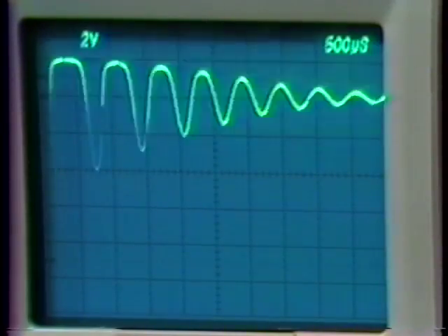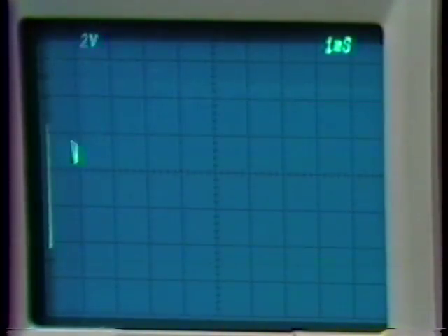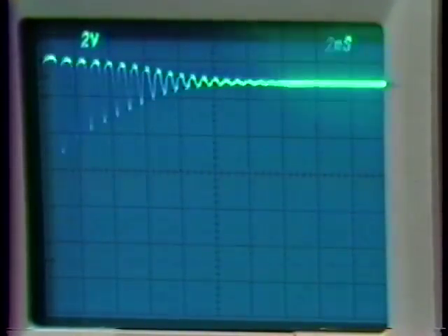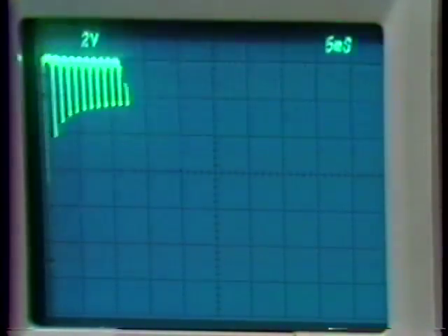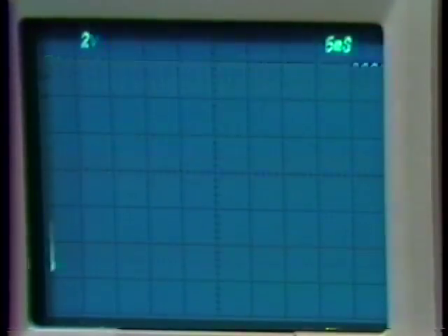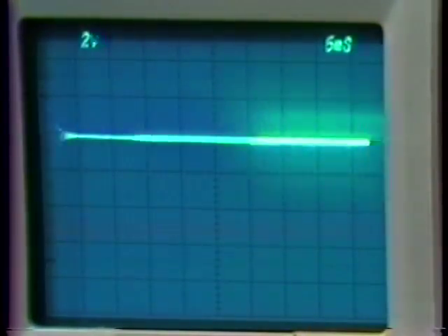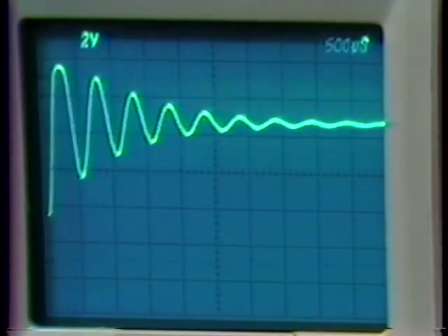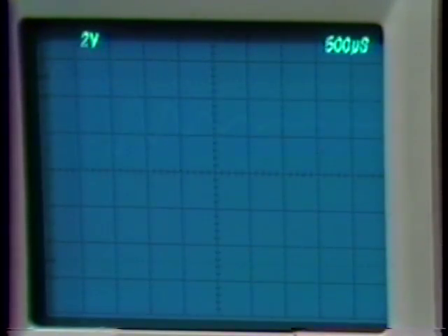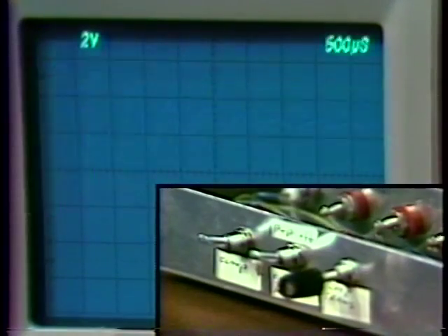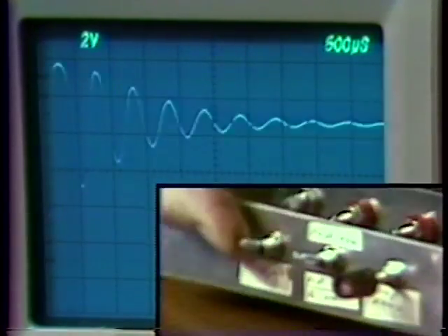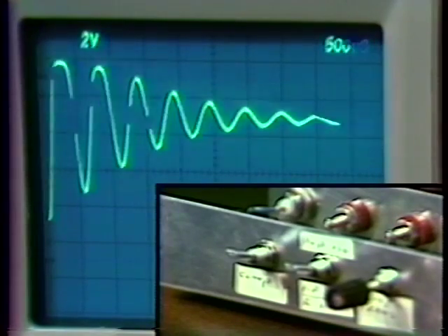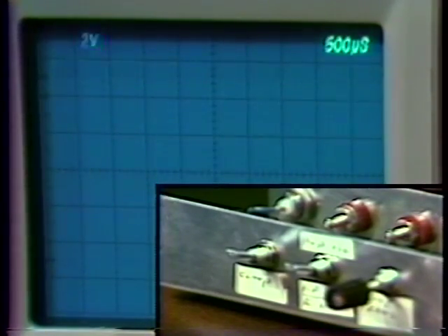We now get to the point that we got into trouble earlier. Well, the waveform gets ugly. There's no doubt about that. We can get almost any kind of behavior out of the waveform while we're driving things. But if I take the input amplitude down once again, allow the system to re-enter its linear region, it does stabilize. Notice the difference with the compensation off. So we'll throw the compensation off, and now let me up amplitude. It jumps into the oscillating mode.